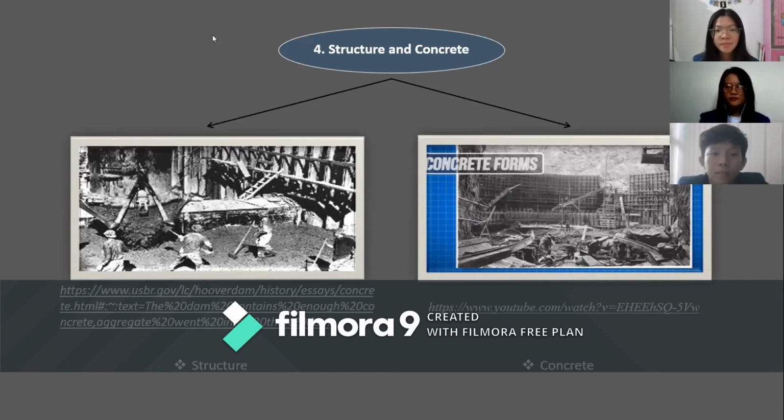Hoover Dam has an arch shape to deflect the force of the water into the canyon wall through the compression of the dam's concrete walls, using the compression strength of the concrete. The concrete itself consists of four ingredients: sand and crushed rock aggregate, water, and Portland cement. This must be mixed in proper proportion to yield strong concrete.